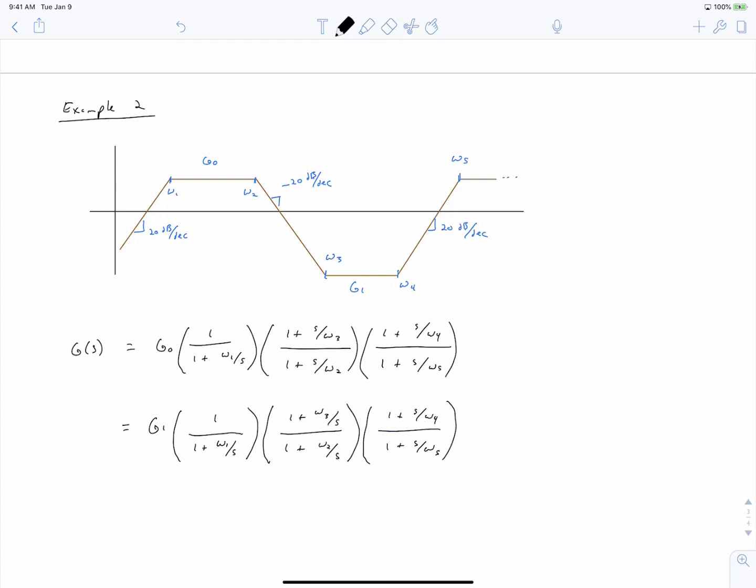Okay, so we're again left with this paradox that we should have gotten equivalent transfer functions, because you don't get to specify both G1 and G0. The relationship is already baked into your transfer function by specifying a gain. You only get to specify a gain in one place if you've specified all your poles and zeros elsewhere in your system. So let's work with our expressions down below.